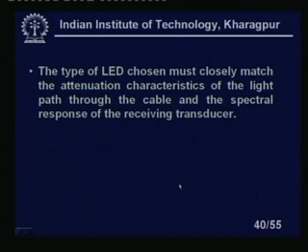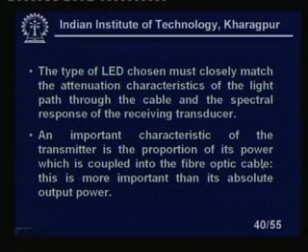The type of LED chosen must closely match the attenuation characteristics of the light path through the cable and the spectral response of the receiving transducers. Because receiving transducers also should have the same characteristics, otherwise they cannot convert that light signal to the electrical signal. Thus, one-to-one characteristics should be there.